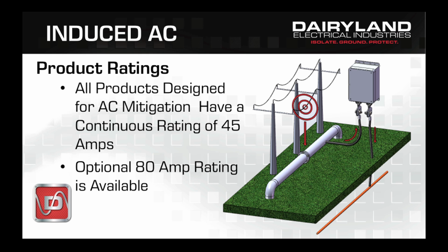Most DAIRYLAND decouplers are rated to continuously pass 45 amps of AC current. Some of our products, such as the PCR, can optionally be built with an extended 80 amp continuous rating. We do have other families of products that can go even higher, but we are not going to cover those in this presentation.